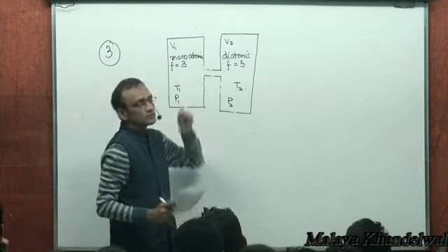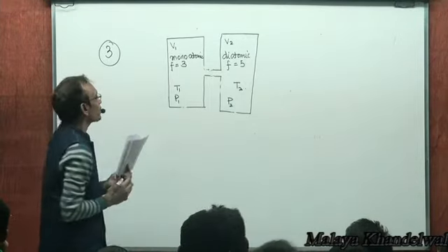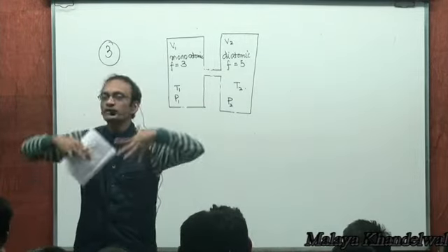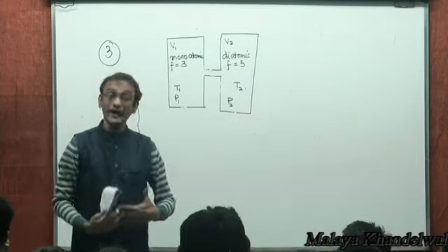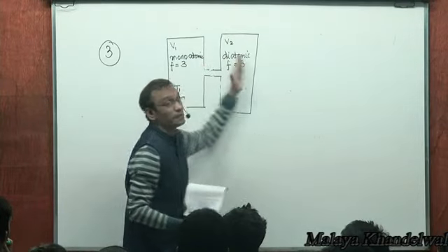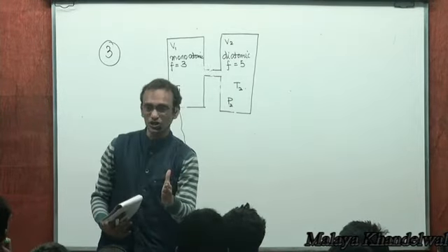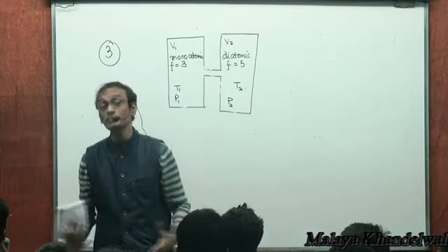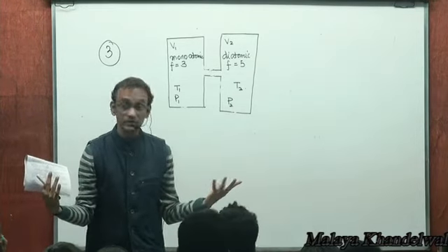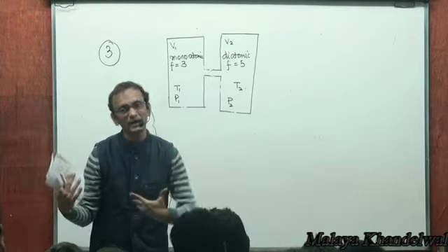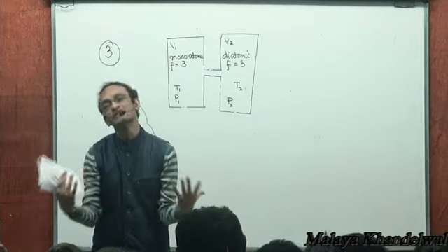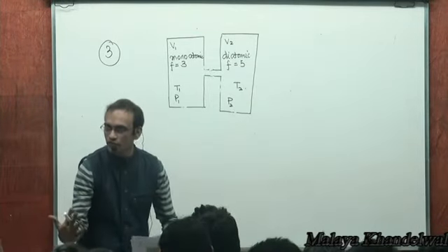See, when they mix, then there would be heat transfer, which would eventually cause the temperature of the mixture to be the same everywhere. So the two gases would acquire the same temperature. Not only that, the flow would keep taking place till such time that the pressures get equalized. That means the pressure in the two containers will be the same. That's thermal and mechanical equilibrium. Mechanical equilibrium means same pressure. Thermal equilibrium means the entire mixture would have the same temperature. That is what you would expect.